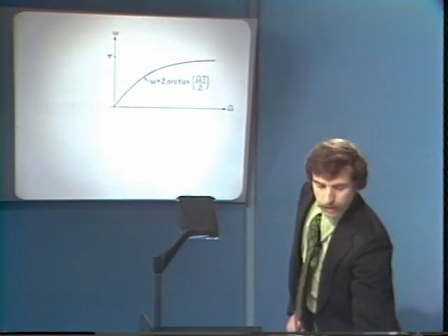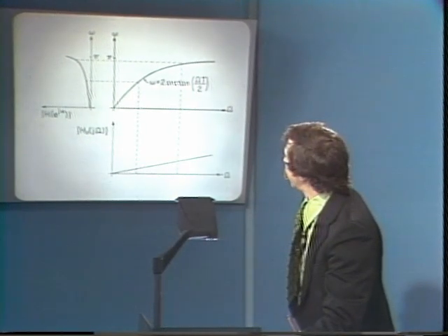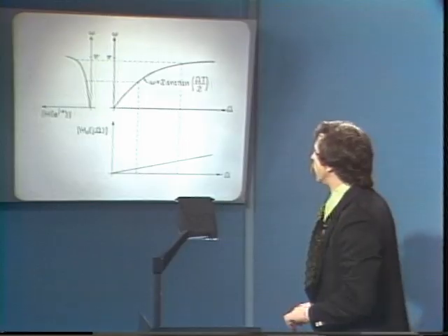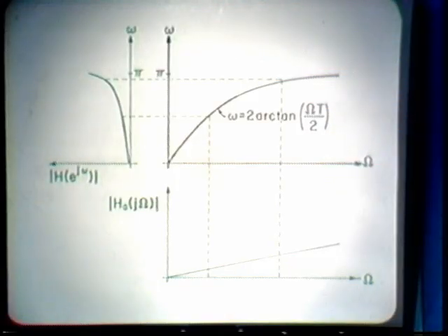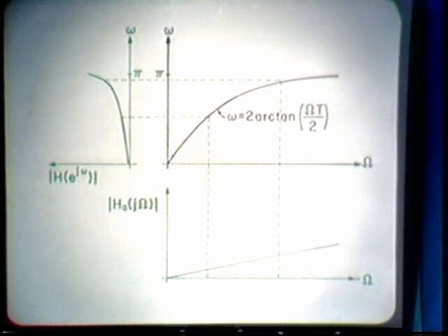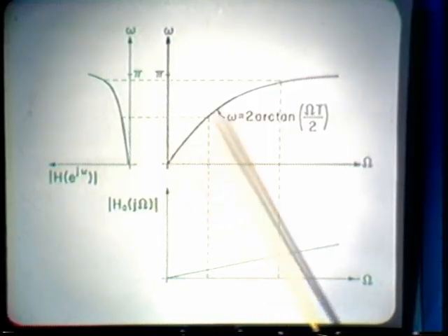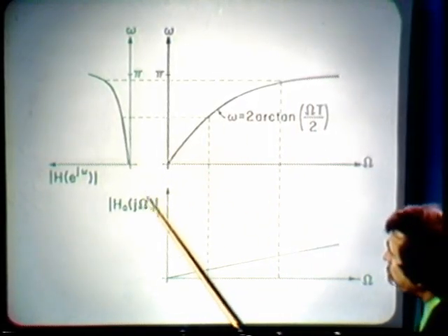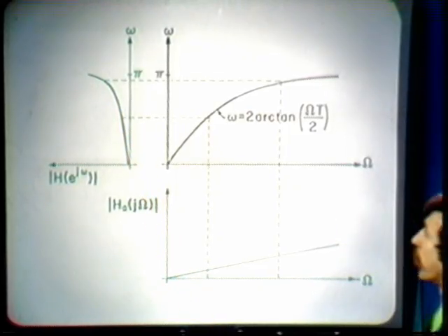For example, let's look specifically at a linear analog frequency characteristic, as I've indicated here, which might, for example, be the frequency response of a differentiator. That, in fact, is the kind of frequency response that a differentiator might have. As we reflect that through this nonlinear curve, because of the fact that that's nonlinear, we don't maintain the linearity of the analog frequency response.